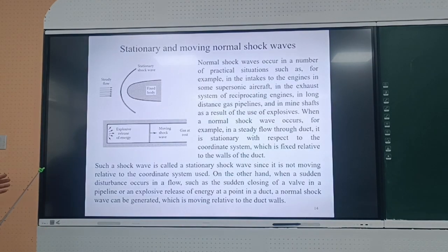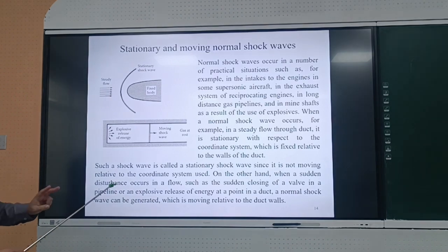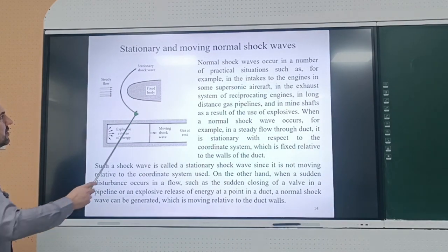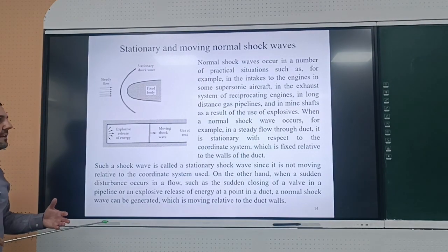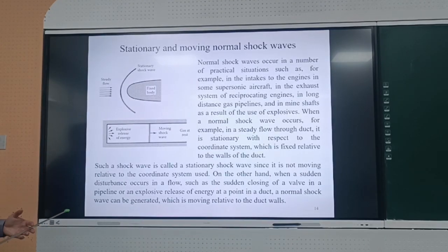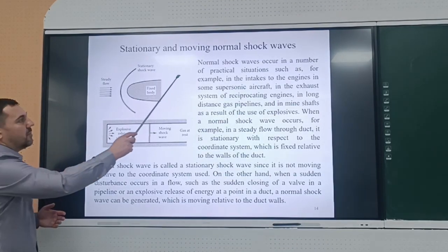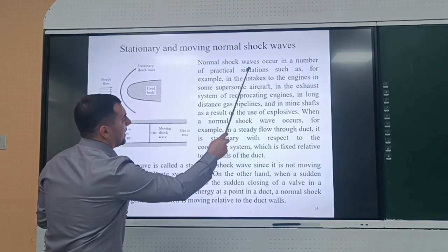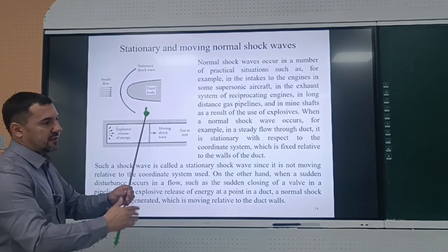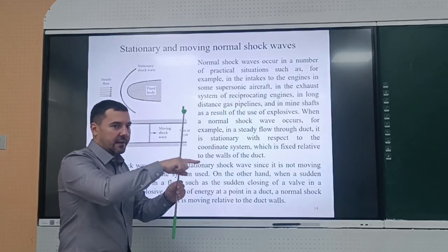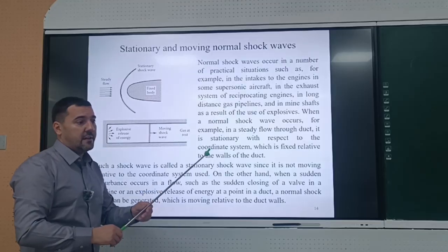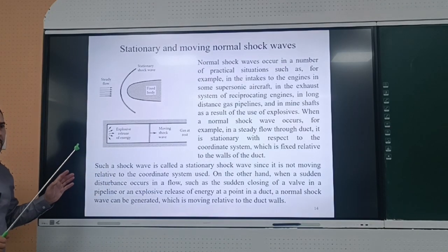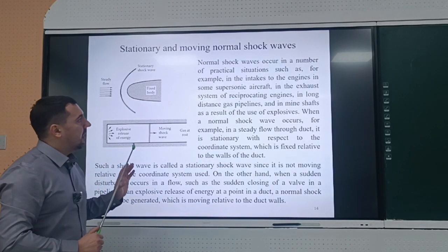In the majority of books, shock waves are usually of interest from two points of view. For sure, this is aerodynamics, and in aerodynamics, usually the so-called stationary shock waves are of interest. The object that we have discussed is also called a normal shock wave. A normal shock wave means that the shock wave front is perpendicular to the direction of its propagation. Actually, there could be oblique shock waves and so on. We're not going to discuss it here because it's not a course on aerodynamics.